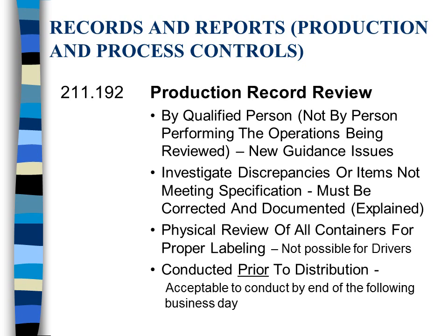Investigate discrepancies or items not meeting spec. They must be corrected and documented. By that, we have an out-of-spec procedure. If you are doing a liquid oxygen reservoir fill, and for some reason, when you do your assay, the assay falls below our guidelines, you must contact a QCU member for additional help.